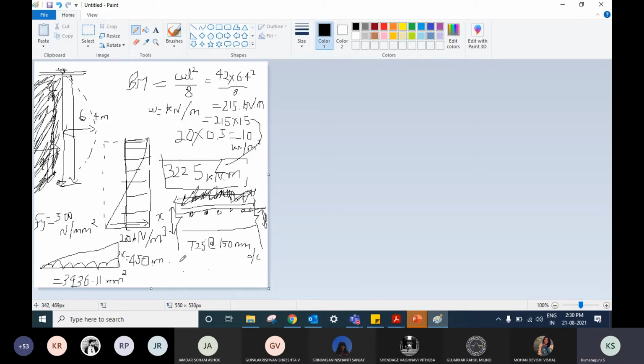Cover to that rebar is 50 mm. Let's say cover is equal to 50. And this horizontal rebar, the running rebar, I'm going to make it a 12 mm diameter rebar, something minimal. So let's just take 12. So that is there. So 12 mm horizontal rebars.